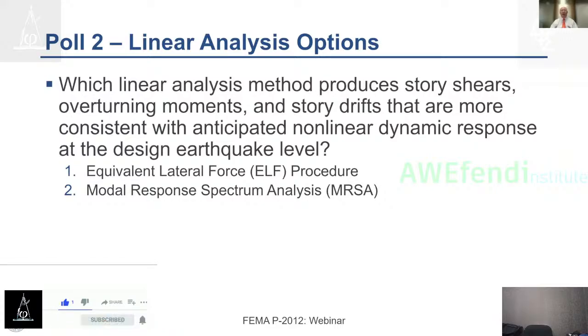The reason being, in part, modal response spectrum analysis is still linear, and when you have an R factor of 5 or 8, the response is definitely not linear, and so the strength matters a lot in a way that the method can't pick up. So ELF does a better job of characterizing the results. It doesn't mean you can't use modal response spectrum analysis. It does give you some insights into the dynamic performance of a building. But the ELF procedure is both more conservative and generally better matches the envelope of results from nonlinear analysis.